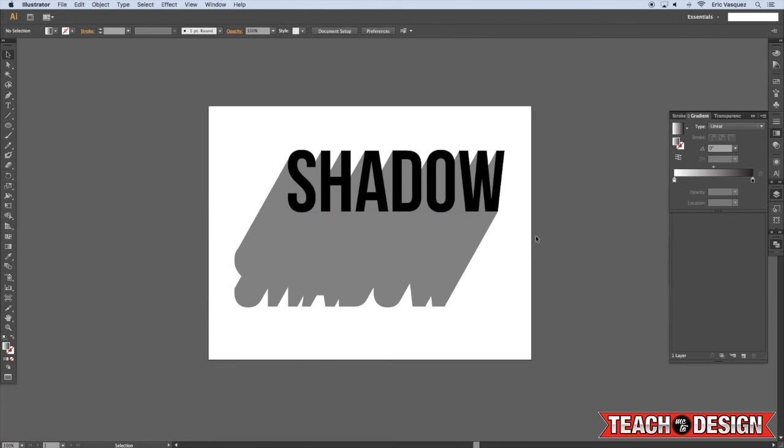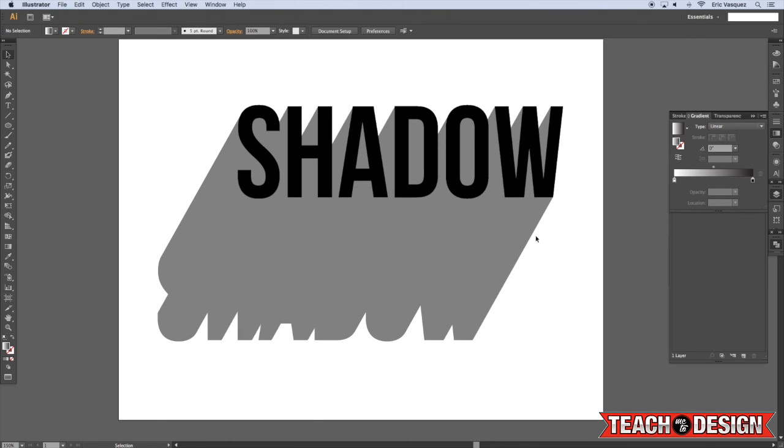You can combine this with other text effects for more interesting results, but I had a few people ask me how to achieve this long shadow effect, so I just wanted to show you guys how I tend to do it in Adobe Illustrator. So I hope that you found this to be helpful.